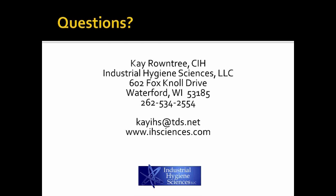How I would do that is I would start out putting a sampling strategy together, focusing on the alloys that have the highest chrome content, especially if you're going to be doing post-casting operations, looking at which ones may have extensive repair welding, or may require a lot more arc gouging or manual plasma cutting, and trying to categorize them.